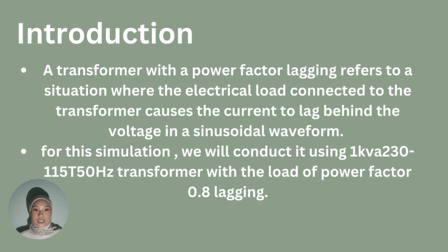For the introduction, a transformer with a lagging power factor refers to a situation where the electrical load connected to the transformer causes the current to lag behind the voltage in a sinusoidal waveform. For this simulation, we will use a 1 kVA, 230/115 V, 50 Hz transformer with a load of power factor 0.8 lagging.